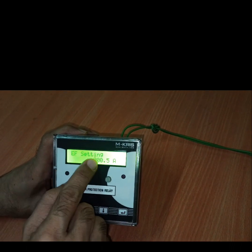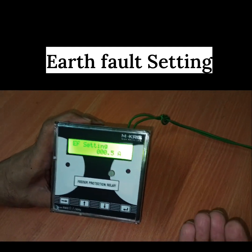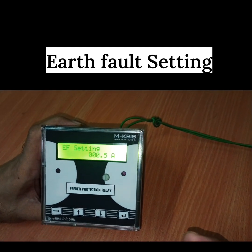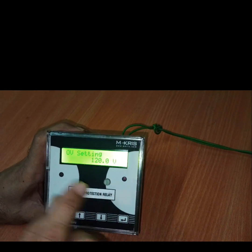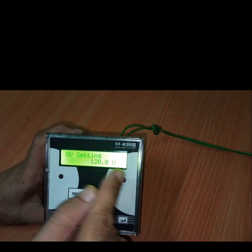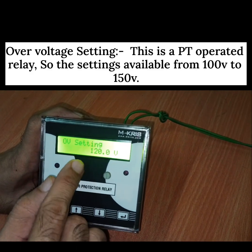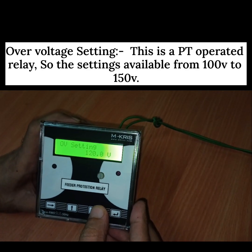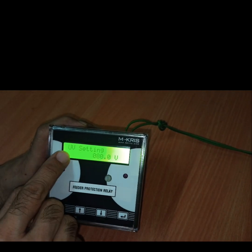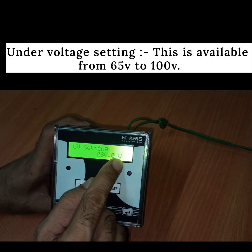Then this is the earth fault setting. This setting is usually made, let's say 10 to 50% of the rated current setting. So this setting is available. Then we have over voltage setting. As this is a PT operated relay, the settings are available from 100 volts to 150 volts for over voltage setting. Then we have under voltage setting, which will be available from 65 to 100 volts.